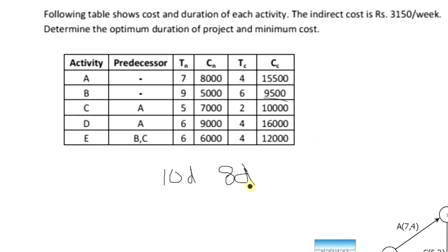That will be the maximum time we will be getting. So in this case, you have to reduce the total duration by 2 days. How can we reduce it? By providing more laborers, more materials, more machinery, etc. Or in general, by supplying or utilizing more resources, we can reduce the time of completion of a project.